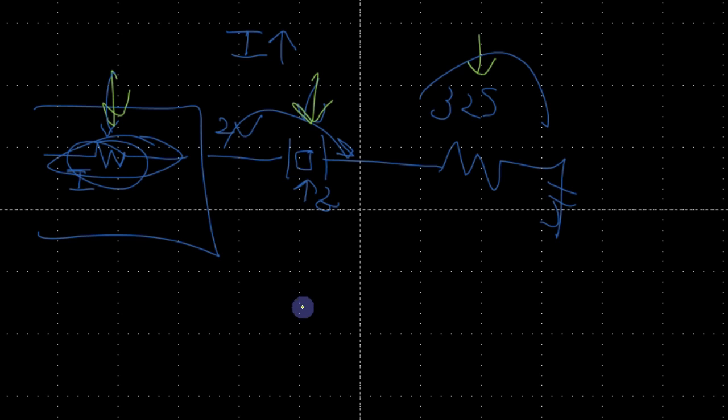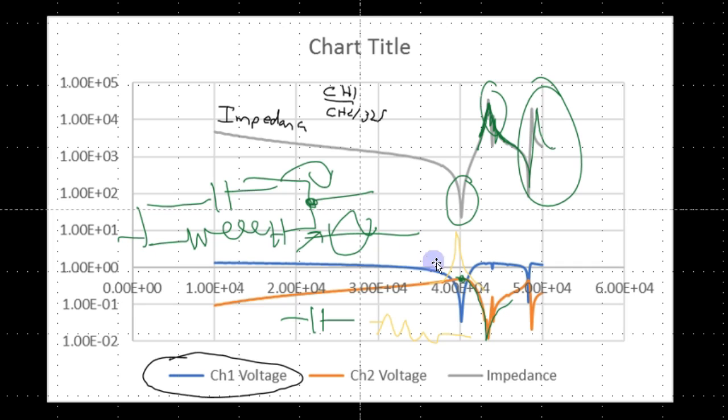However, if we instituted a closed loop control where we actively control the voltage such that the voltage over the transducer was constant, we would indeed see a very sharp peak at the resonance frequency. However, since the voltage was not actively controlled, the system was allowed to do with the voltage as it pleased. We don't see a peak in current, and the voltage is the one that spikes lower due to its dropping over the output impedance, and especially the series resistance.